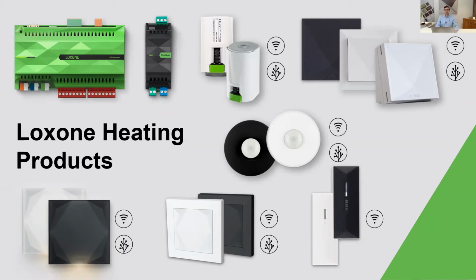Other things to do with heating and cooling, valve actuators. These are kind of the main product you would consider when you're considering Loxone and heating control. We do a valve actuator in Air and a valve actuator in Tree. The Air version can be either powered by 2 AA batteries, or there is a connector here for 24-volt DC. The connector is a punch down, so IDC punch down like you would do in a patch panel.